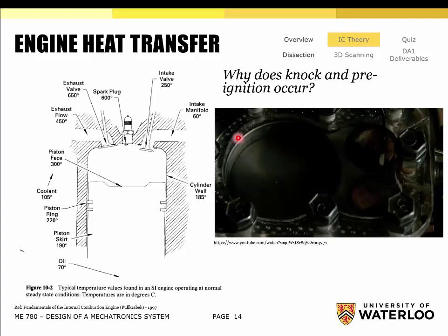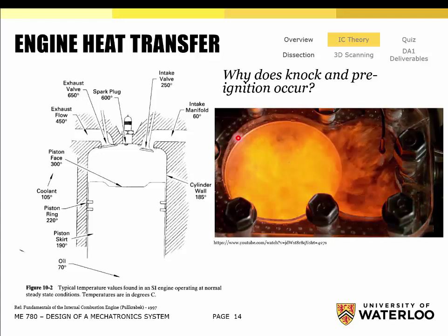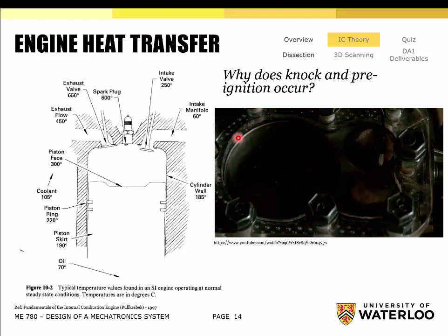So in modern engines, do we inject gasoline directly inside the chamber or outside in the manifold? Excellent question. So direct injection engines, instead of introducing the fuel here, they actually just directly inject it into the cylinder. Okay, so there's some mechanical complexity to that because you're injecting it into a very high pressure, high temperature environment.